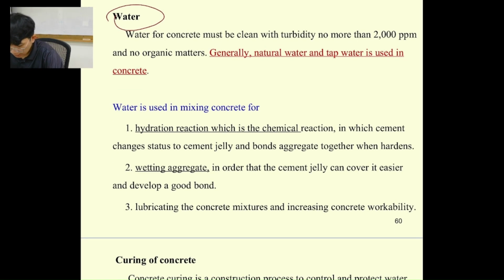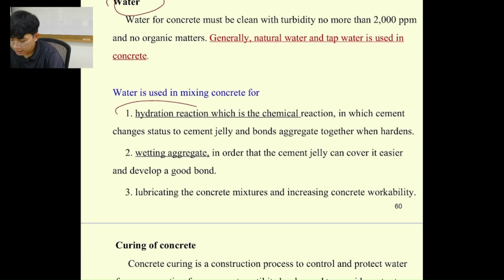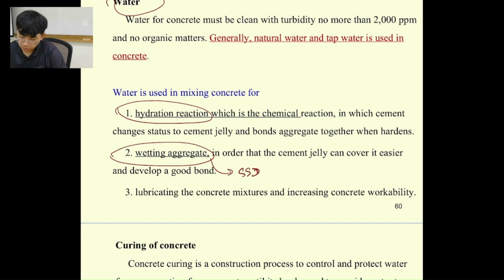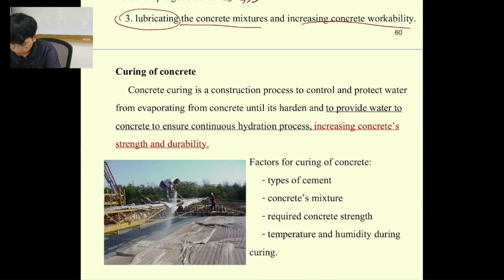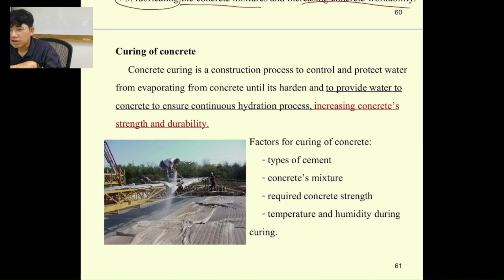Okay, then another topic is the purpose of the water. We use water for the hydration process, and we use water for wetting the aggregate. The one we adjust after the mix design is when we add water to the aggregate to make it wet, into the SSD condition. And the last one is lubricating the concrete mixture. We lubricate the surface and fill all the water inside the concrete, which increases the concrete workability. And curing. For curing, we have a lot of types.